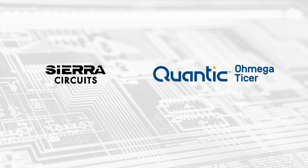And then also the tolerancing, like I said, depending on the size of the resistor and the material itself, we guarantee typically about plus or minus 5%. Then you add the etch tolerance. It can easily go up to 10 to 15% overall, just on the etch tolerance. And so we see a lot of typically 15% to 20% tolerance on a lot of the designs.